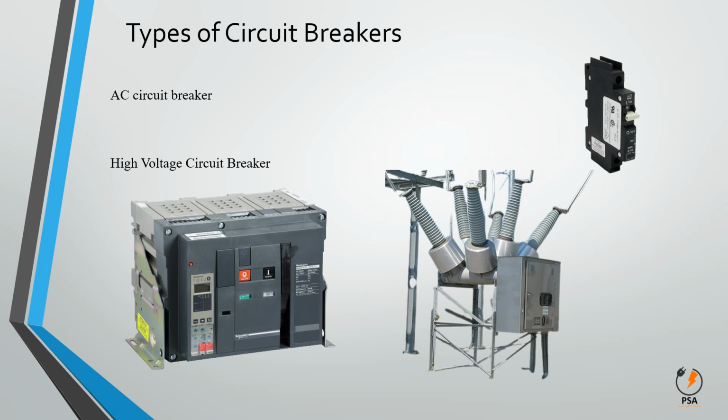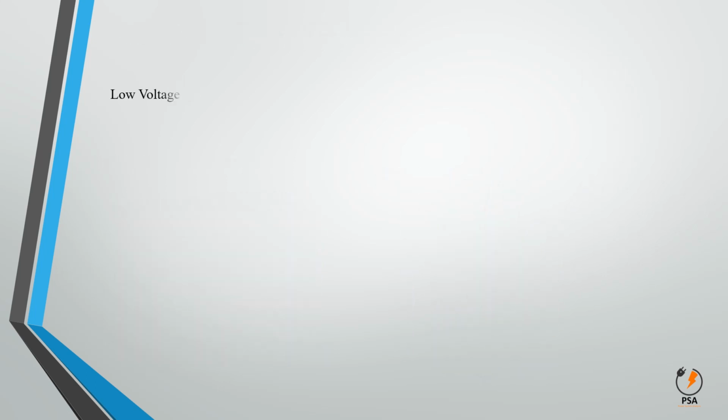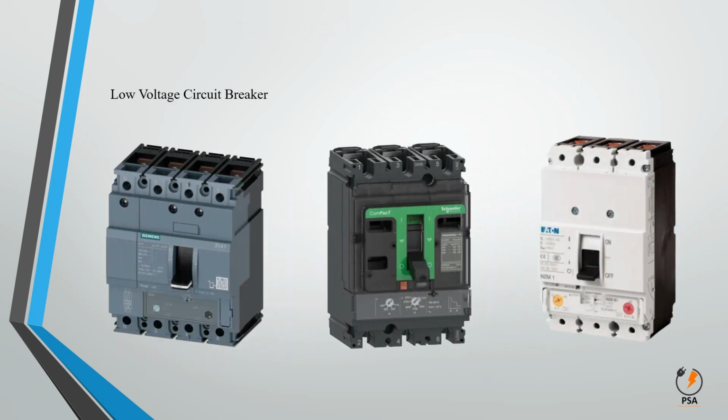These circuit breakers can be arranged to allow tripping of a single pole of a three-phase line, rather than tripping all three poles. Circuit breakers with all three poles are used for certain fault ratings and improve system stability and availability. Low-voltage circuit breaker. A low-voltage circuit breaker is designed for circuits rated 600 volts or less.